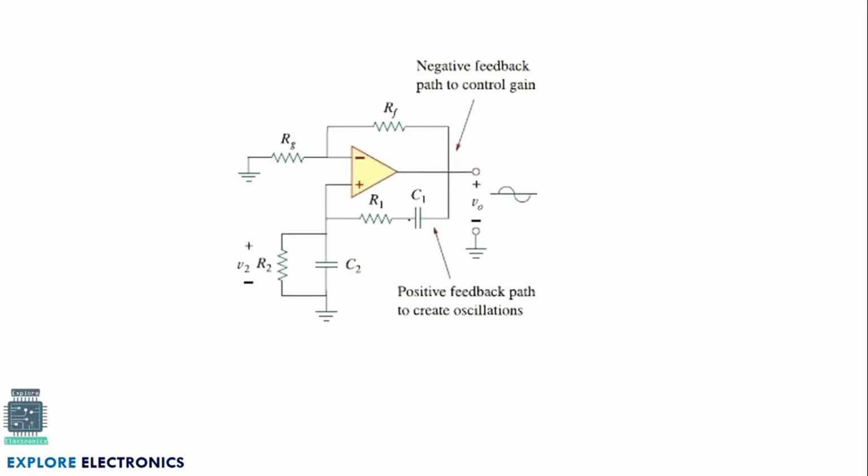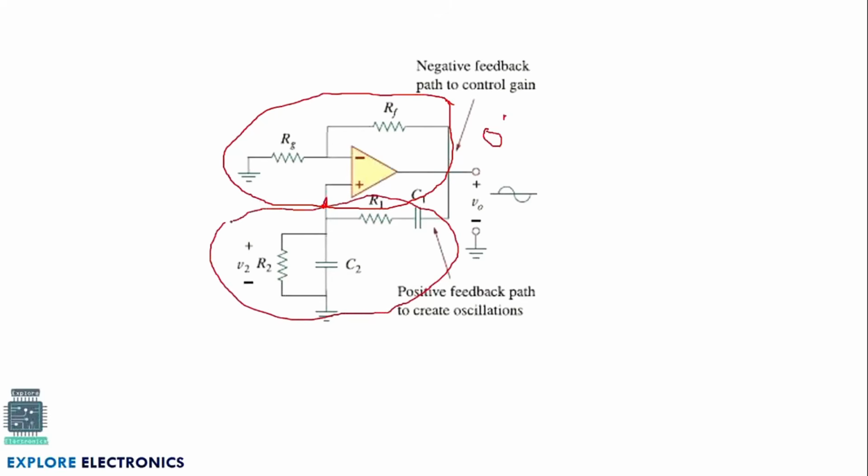You can easily understand here. This is an op amp which is connected in non-inverting fashion. This is the input signal and the inverting terminal is grounded. This will act as a non-inverting amplifier which produces 0 degree phase shift. And the second half of the circuit is the Wien bridge oscillator. This produces again 0 degree phase shift, so that we are going to get a sustained oscillation out of this